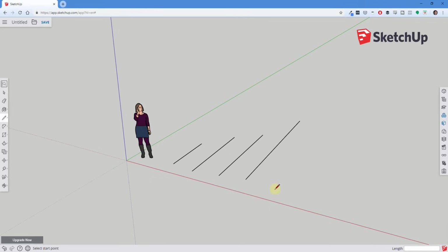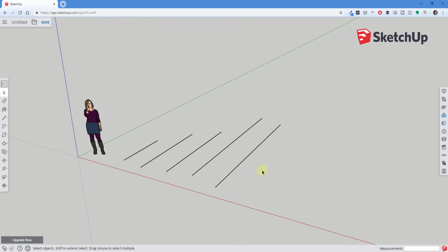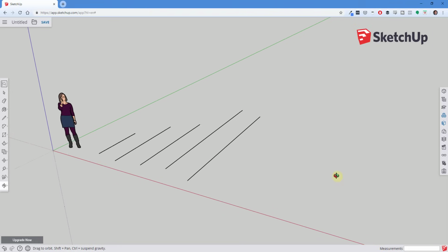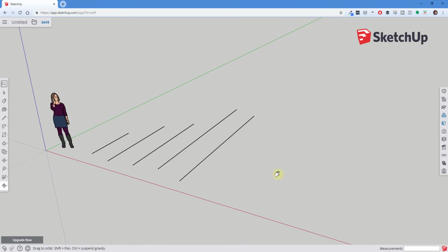But on the other hand, if you activate the line tool by tapping the L key, you single click, and then you move your mouse in this direction, note that now I can type in a value of 15 foot 4 inches and hit the enter key. So as long as you don't click and drag, you can type in values for the dimension that you want your tool to draw things in. And so it's fairly simple to draw lines inside of SketchUp.